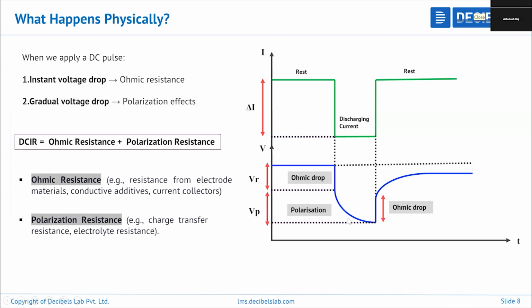Why? Because when you are performing the pulse, at that time your SOC is changing. Suppose you started from 100% and you want to remove 5% in this duration, to 95%. Still, your SOC is not fixed, it is at 98%, 96%, 97%. But when you have completed the duration of the pulse, after that we know your voltage will be at 95% SOC.